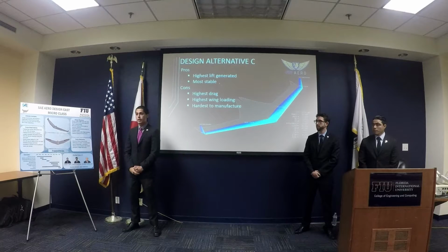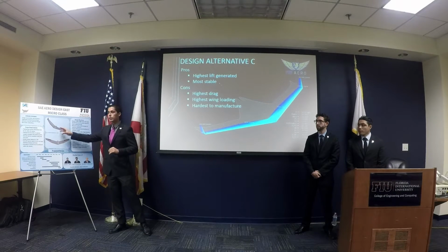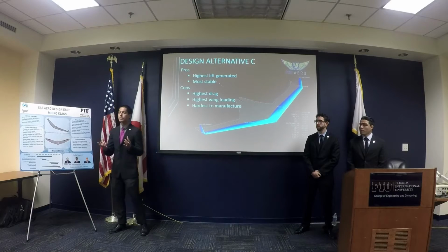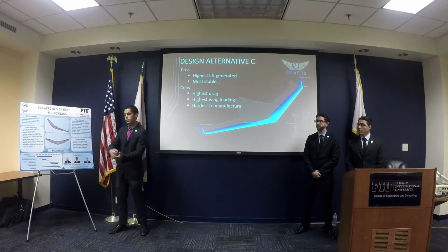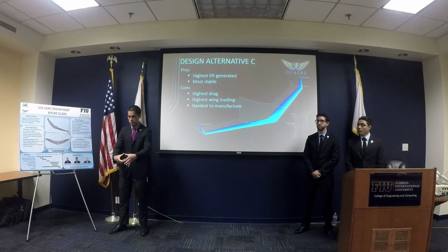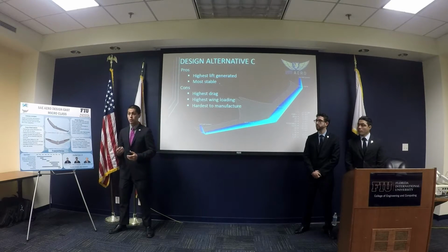It can be either or, depending on your weight analysis, depending if you planned it well. Right now, we're planning on having a modular fuselage. So the fuselage center will be the size of maybe a graphic calculator, and we'll have some sort of struts or inserts. We'll be able to slide the wing outside of the tube. So a 6-inch diameter PVC pipe, you slide out the wing and snap them on, almost like Legos. So that's our initial structural. That's where we want to go to.